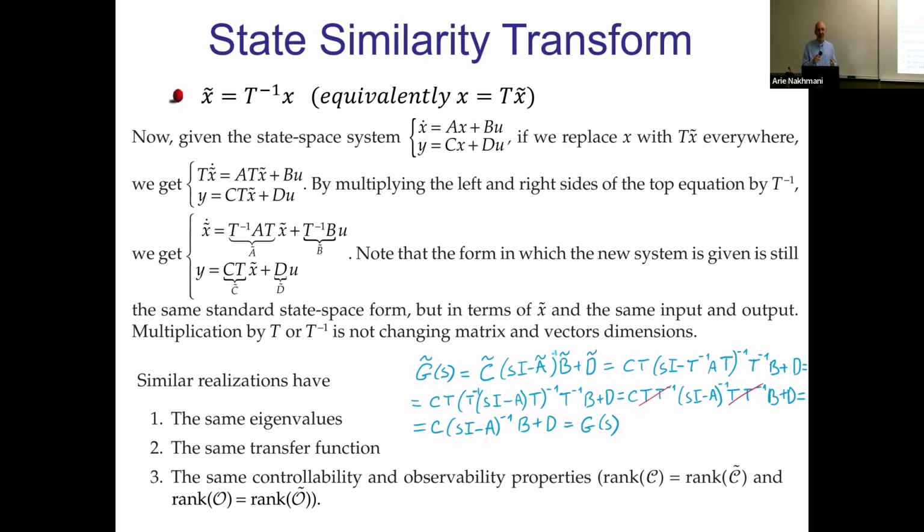So the only difference here is initial conditions, which means that if the system is stable, after some transient response you'll get exactly the same outputs for all of the systems. So the only difference is how you define initial conditions for that system. Other than that, they are completely equivalent in terms of their zero state response.